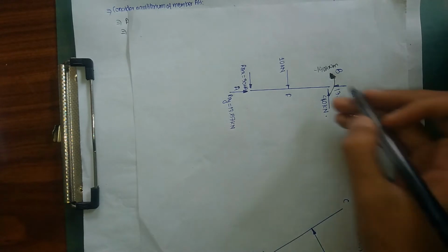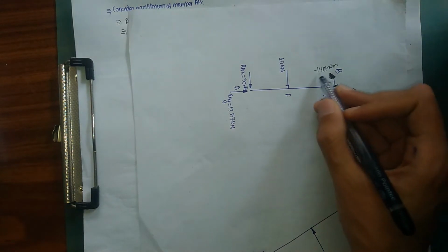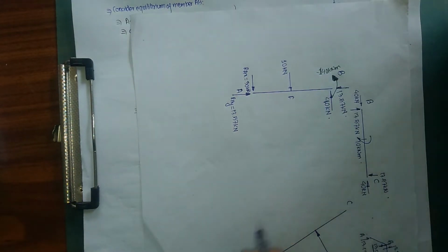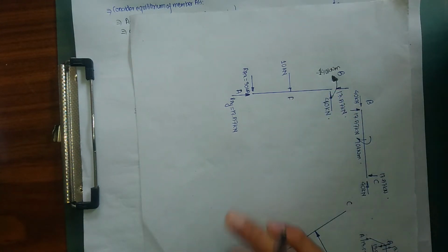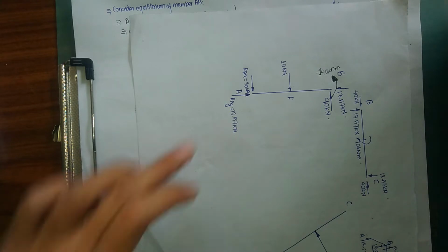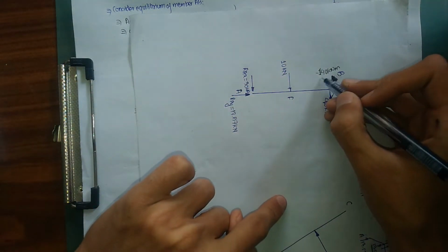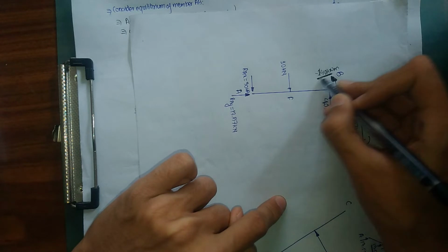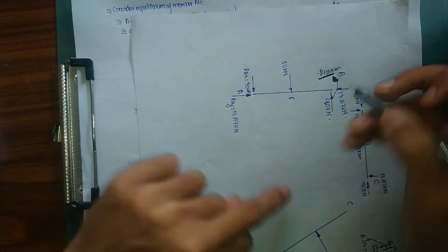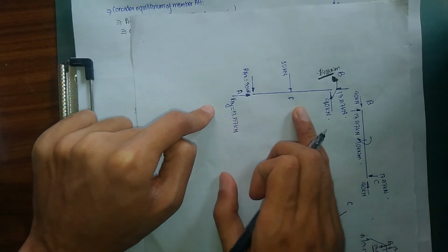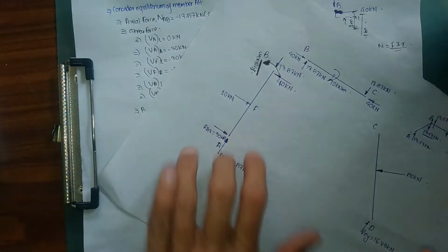So now I have shown my bending moment of minus 140 kN, or hogging, or negative bending, or anti-clockwise moment at joint B. Now another important point of a joint is that a joint transfers bending moment. Simply put, our joint transfers our moment. So this minus 140 kN meter, acting in anti-clockwise direction for our member AB, is going to get transferred to our member BC as well, because of our joint.